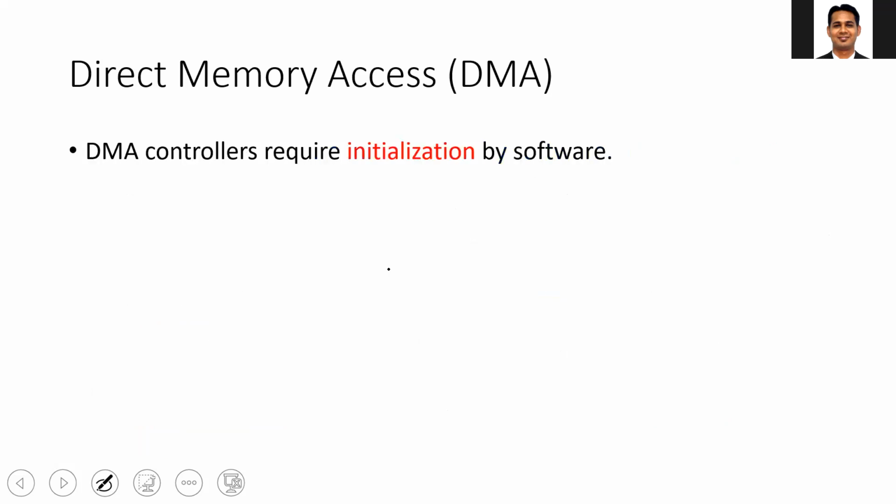So as we discussed, DMA is not an intelligent device. It is just a co-processor. It performs the task assigned to it by the processor. So the DMA controllers require initialization by your software, that is your processor.